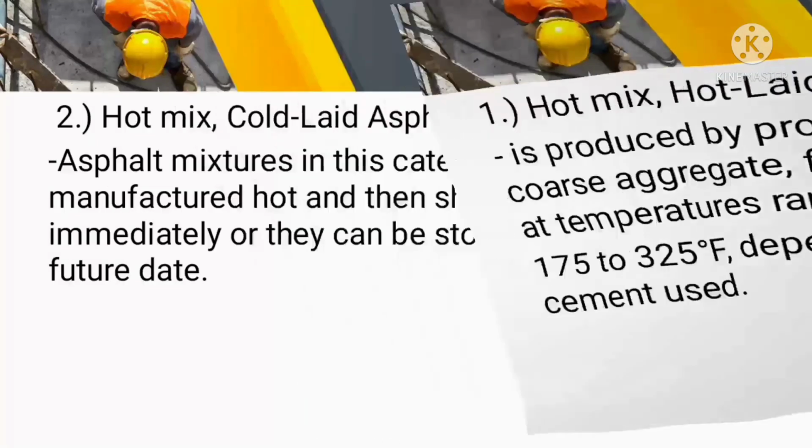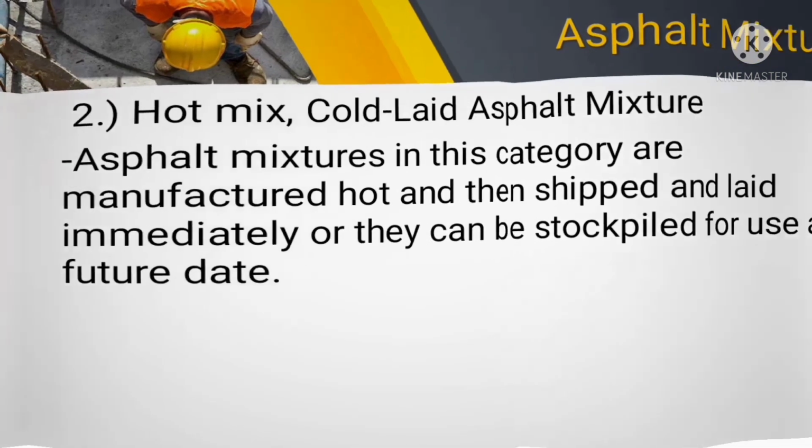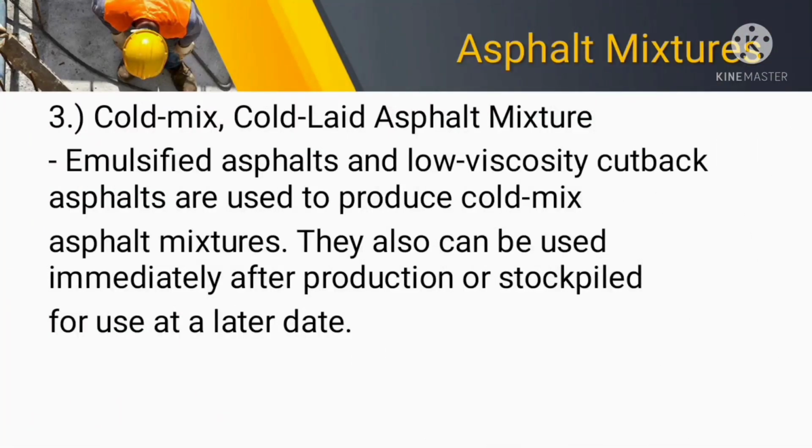The next one is the hot mix cold laid asphalt mixture. Asphalt mixtures in this category are manufactured hot and then laid immediately, or they can be stockpiled for use at a future date. The last one is the cold mix cold laid asphalt mixture.